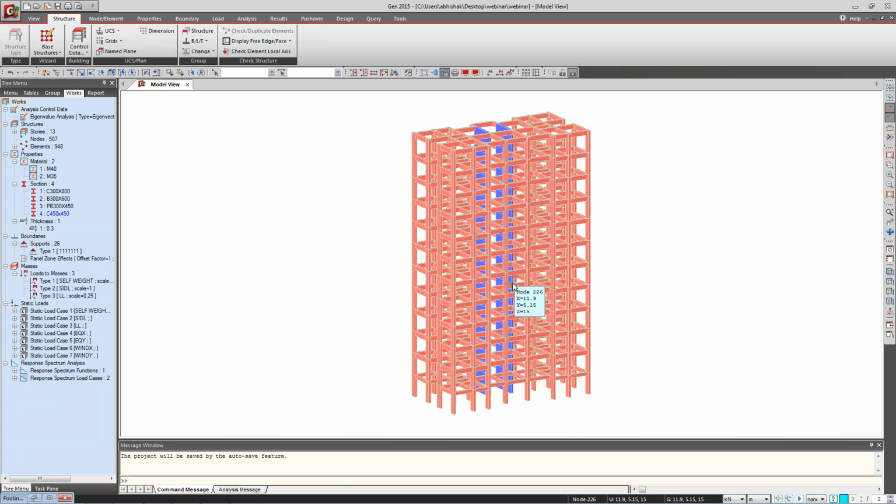Then it considers the total length of the member from 0 to terrace level, whatever height you mentioned. But if there are joints in between, it's a continuous member, so it transfers the load from one point to the other points, and that is considered by the program. If you see the moment diagram also, you can realize how it is calculated by the program.